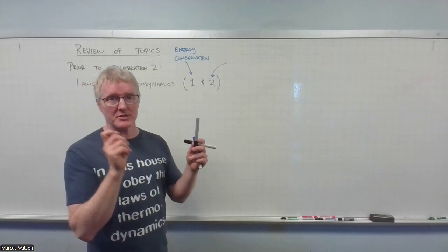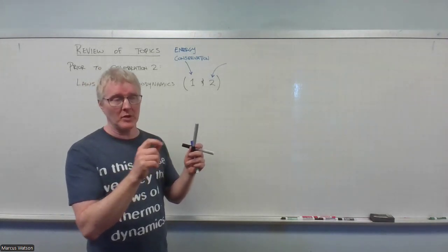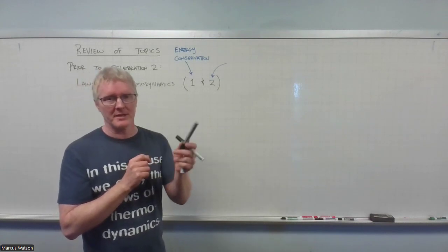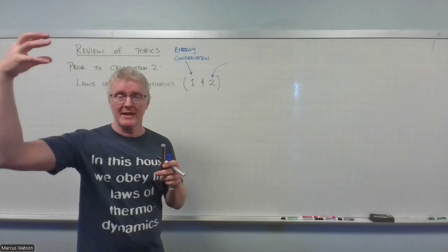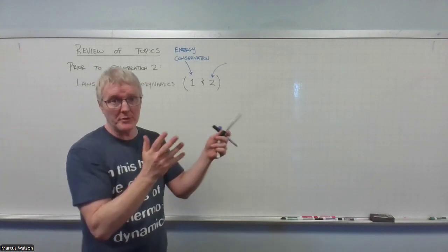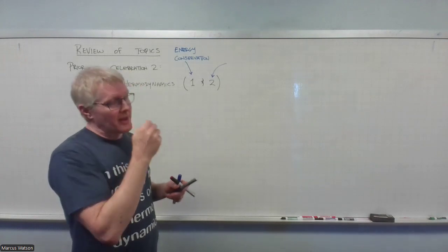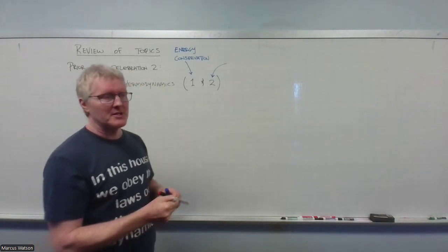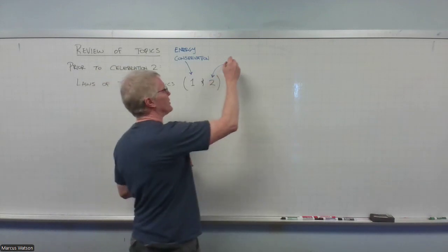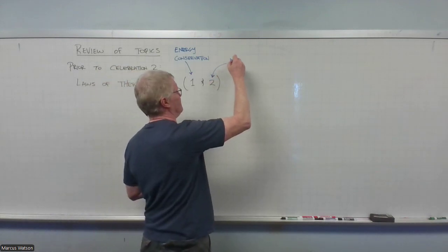The Clausius interpretation of hot to cold heat flow and the Carnot interpretation of no 100% perfect engines. In other words, heat in, 100% of that to work out. We showed that those were the same. Ultimately, through the work of Clausius, the thing that law 2 turns into for us is the law of increase of entropy.